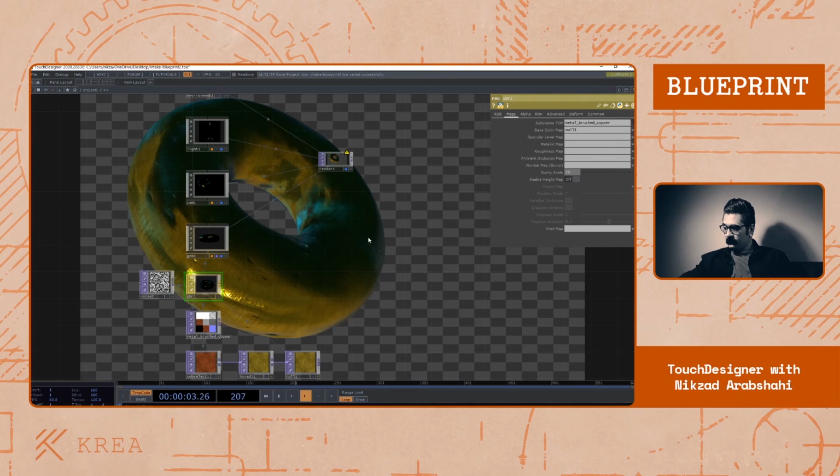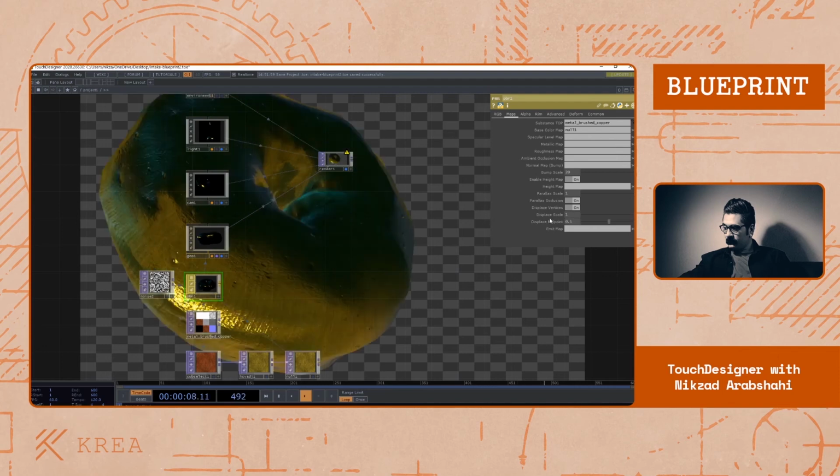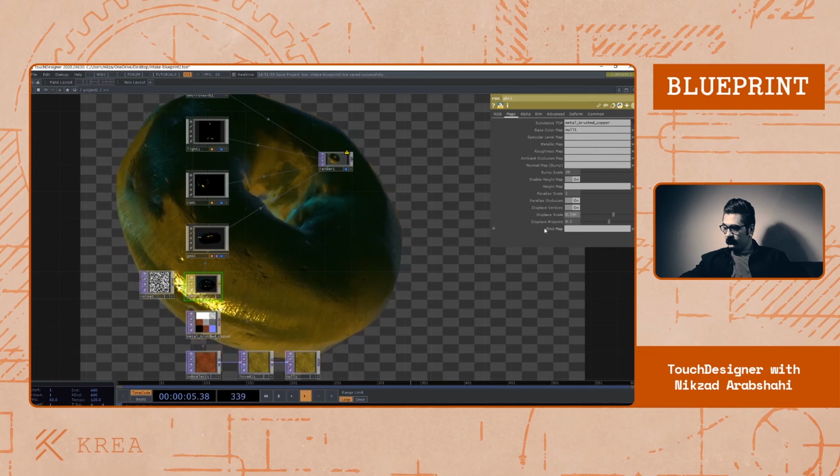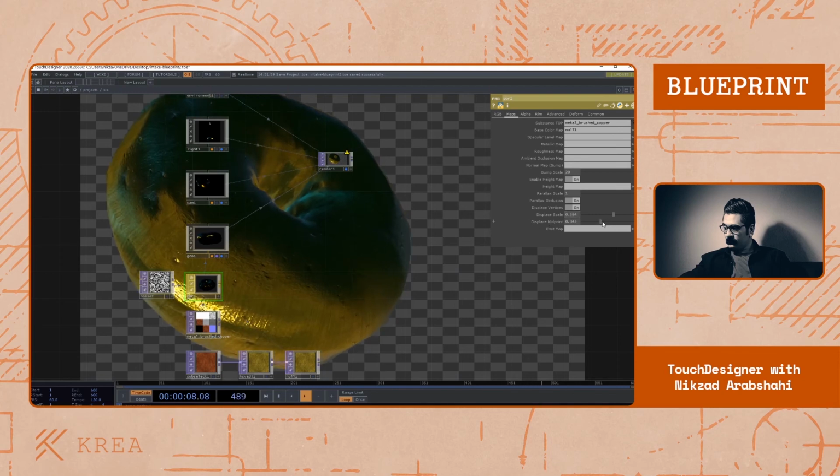I like it. The other super nice feature of the PBR material is this Parallax Scale. Parallax amplifies the value that is applied to the height map, but you need to first enable the height mapping. So let's enable it, and then you need to enable the parallax and these two, and then you can start playing with the displace scale and displace midpoint.